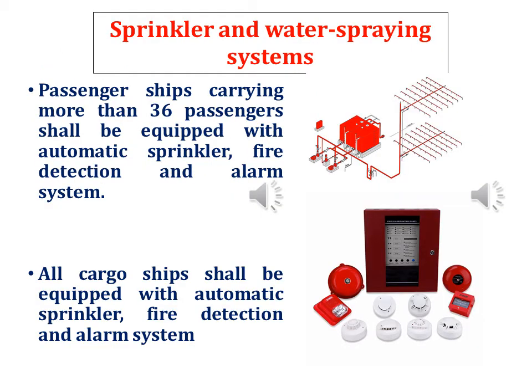Sprinkler and water spraying systems. Passenger ships carrying more than 36 passengers shall be equipped with automatic sprinkler, fire detection and alarm system. All cargo ships shall be equipped with automatic sprinkler, fire detection and alarm system.